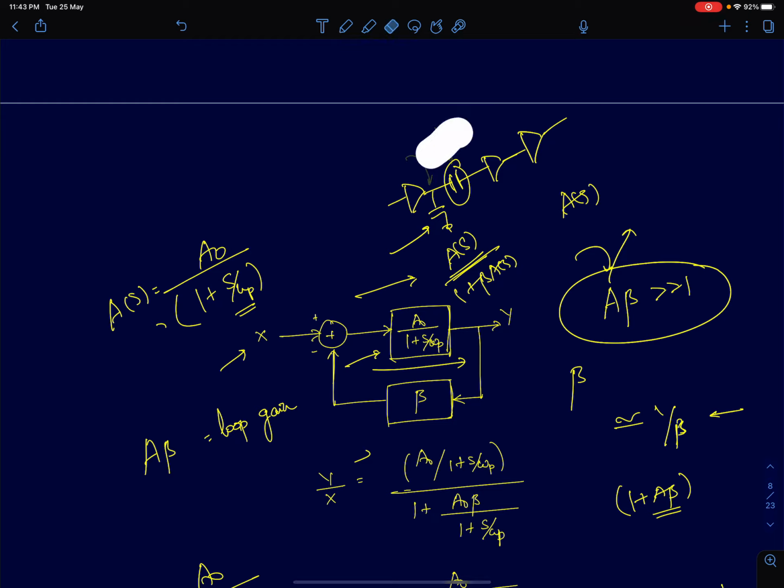They were expecting that, since the bandwidth was decreasing because of the loading of these coupling capacitors, the bandwidth of the amplifier should decrease. But instead, what they were observing, once they put these amplifiers in negative feedback, is that the bandwidth was increasing.